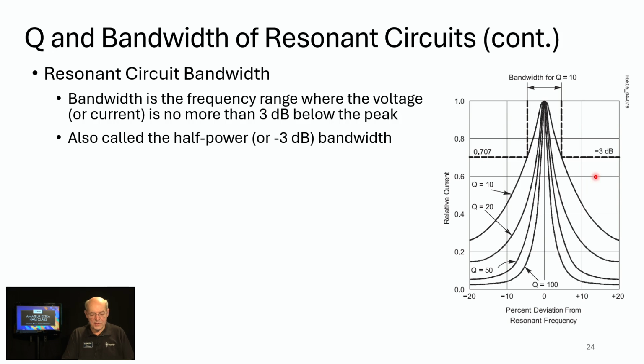For single sideband, you'd want about a 3 kilohertz bandwidth. Let's call this really narrow one in the middle about 150 hertz of bandwidth from this point to this point. That would be a very good selectivity for a CW signal. So grab that concept to start with, and then let's go through some of the detail.